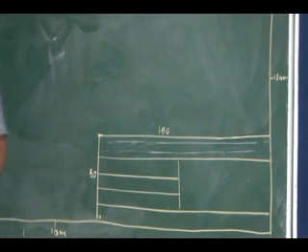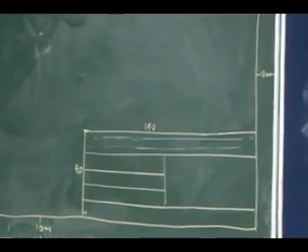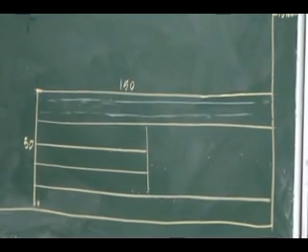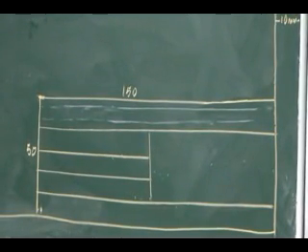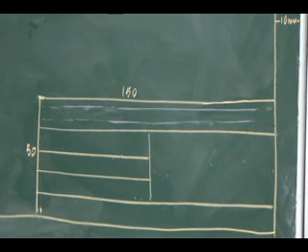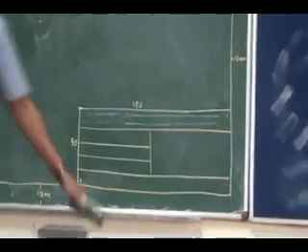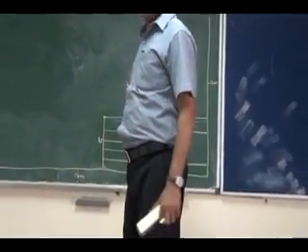Why am I using a white line? It is going to be a very thin light line, so you have to use a pencil with less hardness value, that is a 2H pencil. So far you have used HB pencil, and this is the lightest one, so you have to use a 2H pencil. Any construction lines, any parallel lines which you are drawing for writing, should be drawn in 2H pencil.